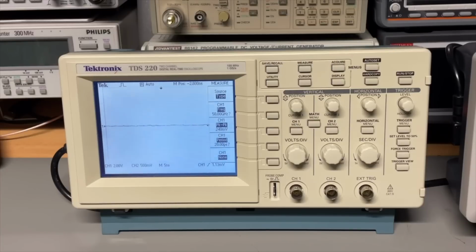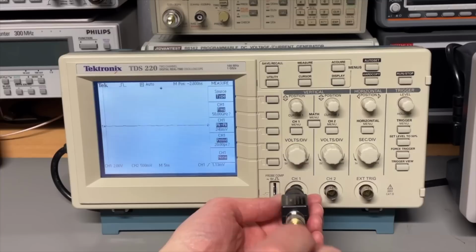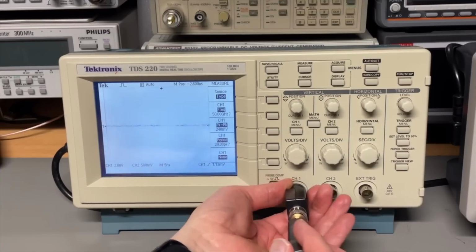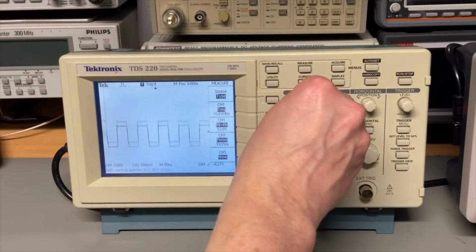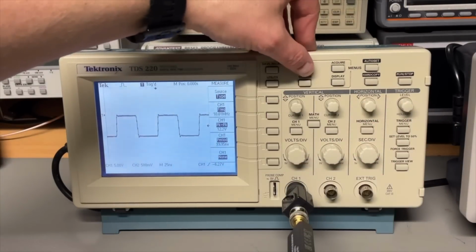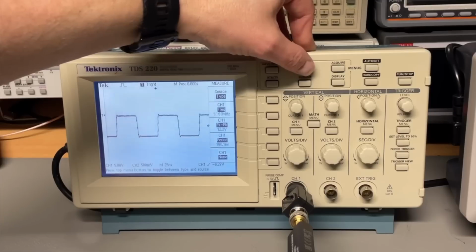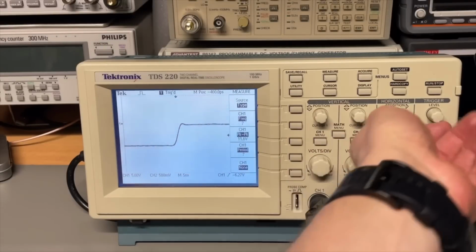I have here a lot older oscilloscope, also Tektronix. It should be able to get up to 100 megahertz. So I use the same pulser, and let's see. I am not sure this one has the proper measure menu that we can see the rise time. I think we need to try to see that ourselves. The measure menu doesn't give us rise time, but we should be able to determine it.